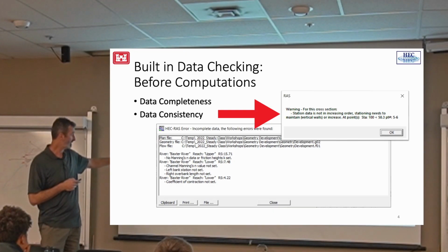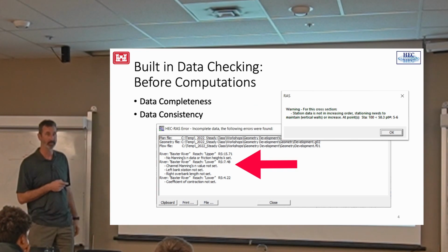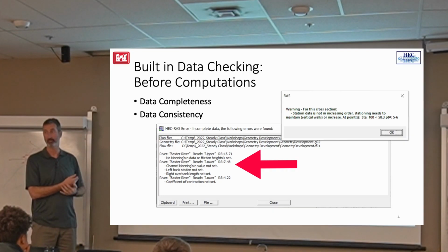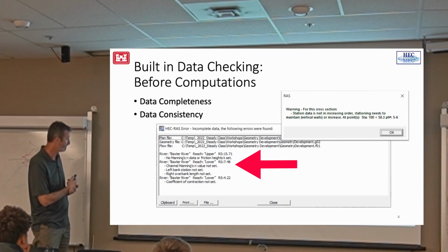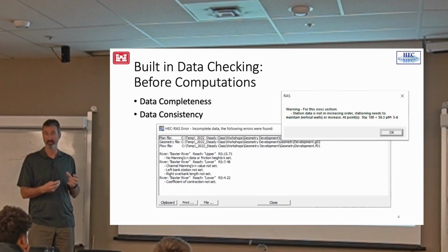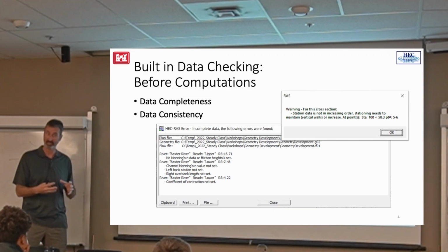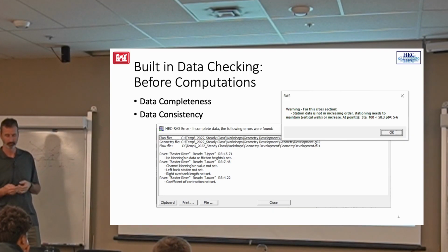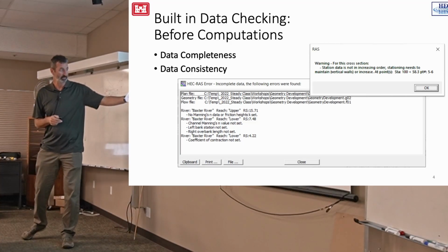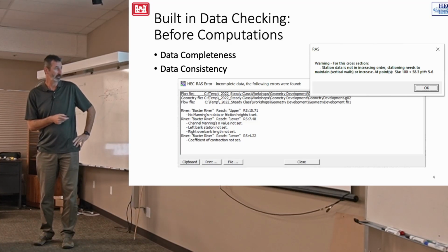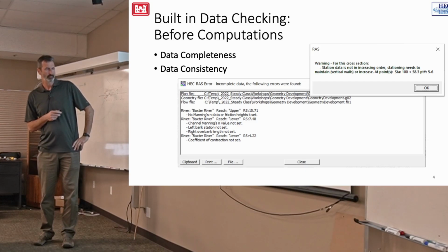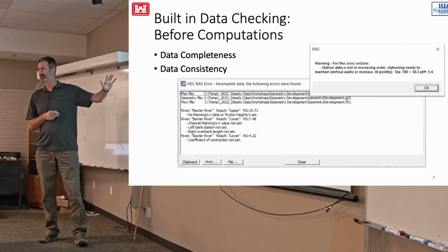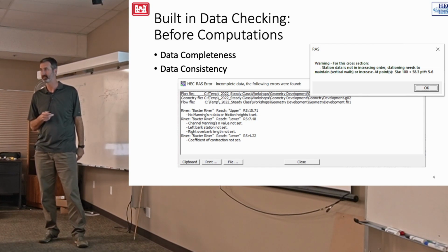So that's that level. Now this other one, this is what always happens before any run, and it goes through the whole data set and looks at every parameter that is going to be needed for that run. So at that point, when you're going to make a run, we know what you're going to do. Are you going to be doing a steady flow run, in which case you need to have all these parameters, and if you do unsteady, then it's those parameters plus a few others. But if you're missing things like you don't have any n values set, then this is the kind of messages you get. We've had requests over the years that, hey, if you have an error list, can I double click on it and it'll take me to that problem? That's a really good idea, and we'd like to do that, but we didn't set it up just to do that.